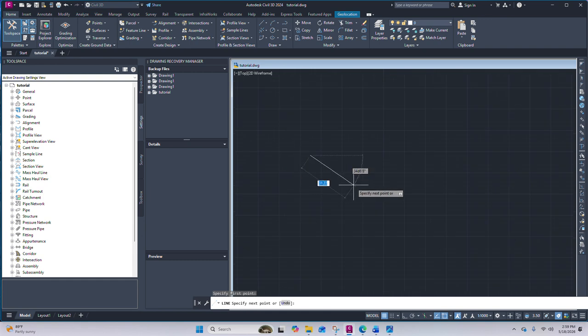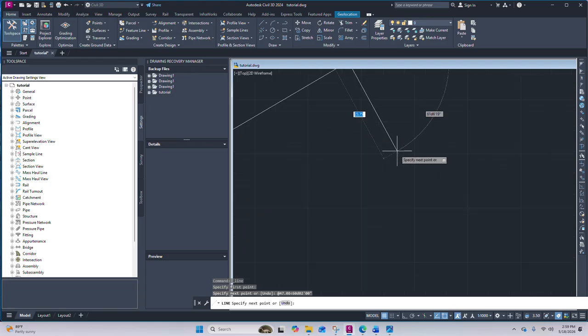The original point will be the L3. So let me start with the 47.08. Then from my keyboard I will press shift, then the angle symbol, then 60 D, then 02 minutes and 00 seconds, then click enter. So that will be my L2.